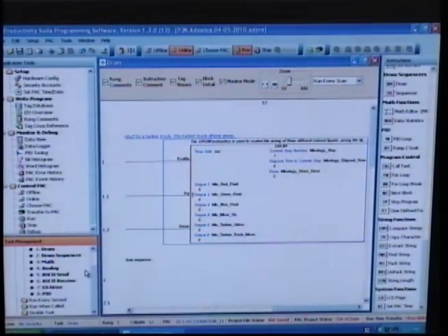I'm going to put the GS drive back where it was, but that was basically just click and drag. Yep, and this is beautiful. I know with DirectLOGIC, a lot of times when we're on phone support helping customers, we would give them the little trick of sticking an end statement in between part of the logic to try to troubleshoot it. And with the Task Manager, if you're structuring and controlling the way you write your ladder logic, you can use this to troubleshoot with. So that kind of covers those points.